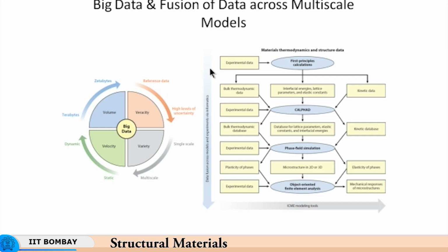So, CALPHAD will give you many parameters here, which when fed to phase field simulation will be able to predict the proper microstructure, properties of elasticity and plasticity of different phases, and then this in turn will be able to predict what kind of properties and what kind of mechanical behavior the material will have at the time of loading.